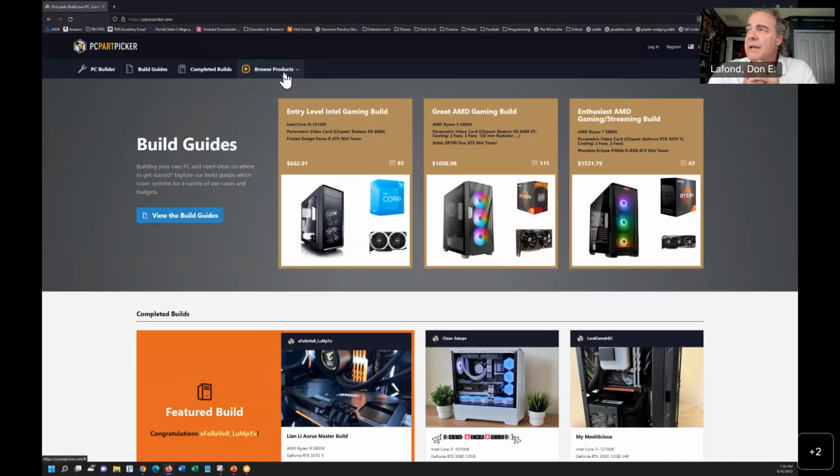Ultimately, you just start with something. You can start with a motherboard that you want. You can start with a processor that you want. For me, I started with my case. I had determined which case I wanted, a Thermaltake 900, and I love the case. And that Thermaltake 900 only allows certain things: the size of the motherboard, the size of the fans. I have a radiator for water cooling. Ultimately, I had to go through the design to make sure it would fit.